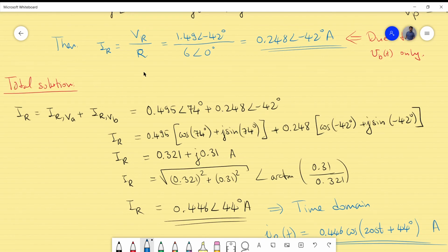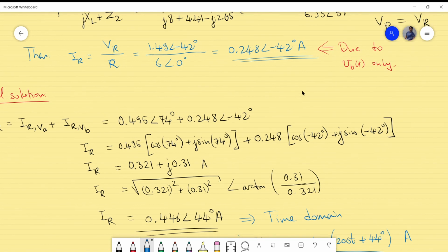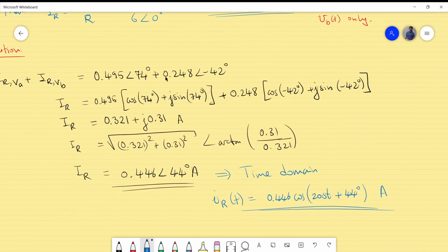And that's actually for this example. So you know the net effect of your system by dividing your complex system, in this case, into very simple circuits, and you calculate the separate effects only due to VA and only due to VB, and then combine them together linearly because it's a linear system, and you add them up and you transform back to the time domain. That's actually the whole business here.